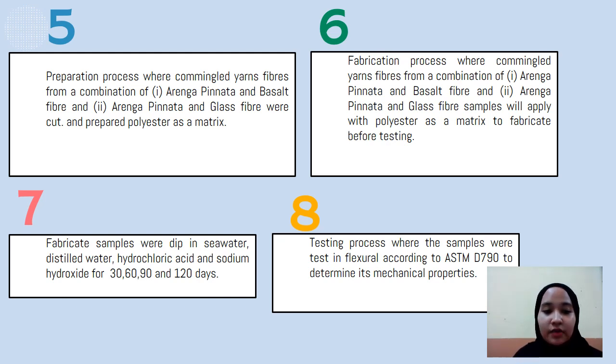Next, fabricated samples were dipped in seawater, distilled water, hydrochloric acid, and sodium hydroxide for 30, 60, 90, and 120 days. Lastly, the testing process, where the samples were tested in flexure according to ASTM D790 to determine their mechanical properties.